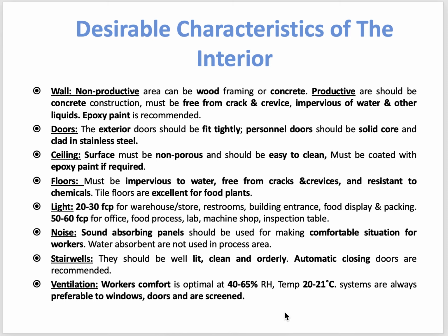Also, if the relative humidity is very low, less than 40%, again it becomes uncomfortable. It's an extremely dry condition, and you may feel a burning sensation, because if it's very dry, our throat will become dry very quickly.